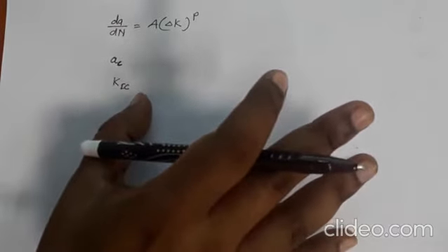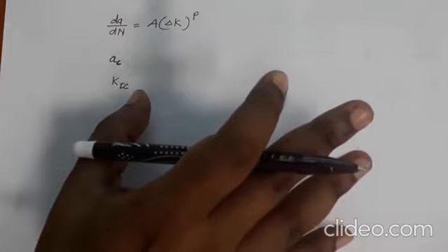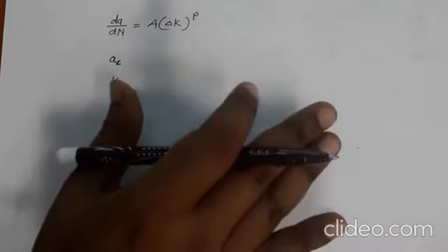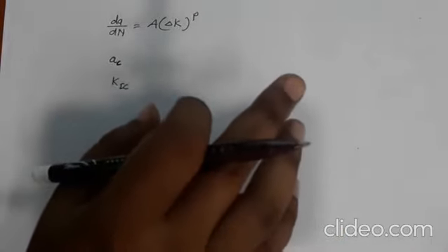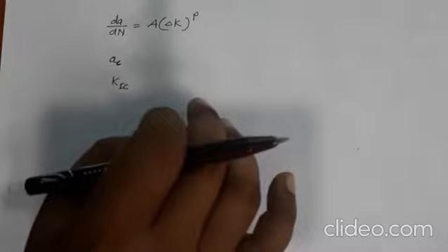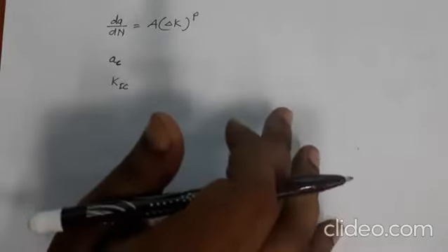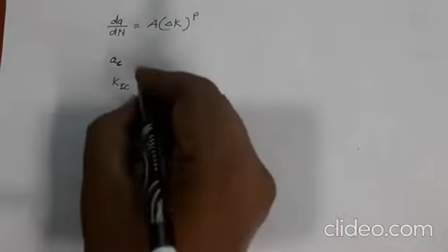Why do we deal with mode 1? Because mode 1 is the conservative approach, meaning that mode 1 is the worst scenario. So if we are safe in mode 1, we are safe in all other scenarios as well. This is why K1C is more important than others, because that is the worst case scenario as far as safety of the structure is concerned.